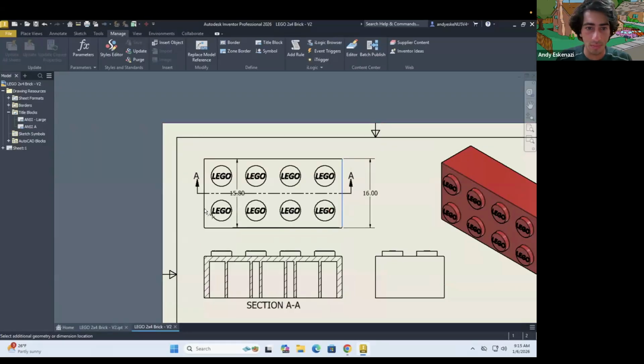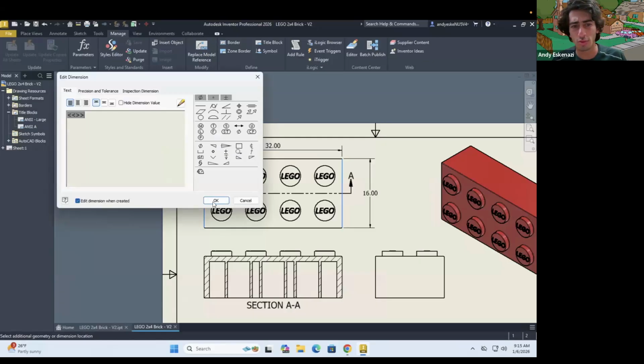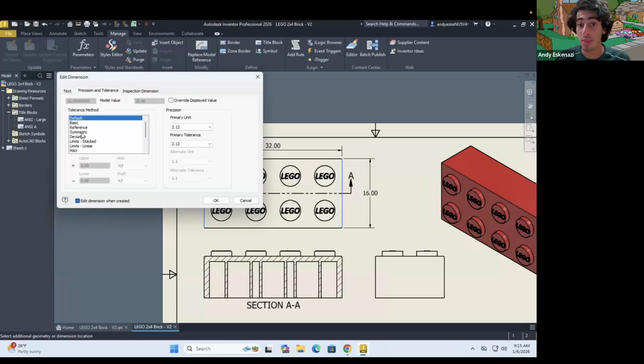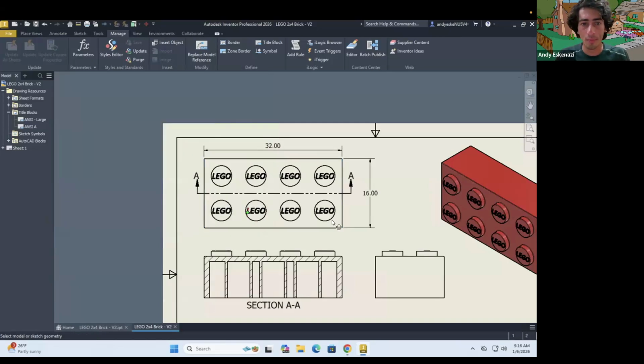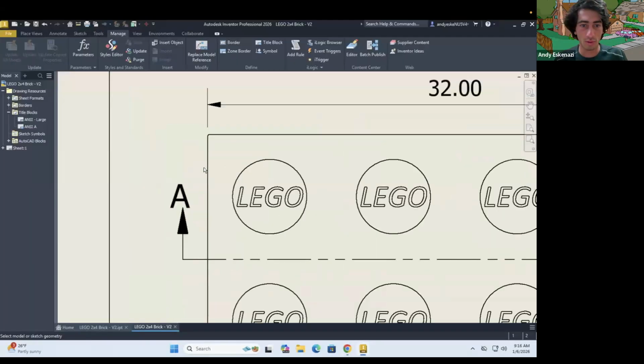So then I go here to D, and we can continue adding more dimensions right there. In fact, you can also specify whether you want these to be 2 decimal places, or since we're here, I can also specify the tolerance. Because if this is manufactured and it's using some manufacturing tolerance from whatever tool that you have, you can say, right, maybe go up to 2 decimal places plus minus a certain amount that you are allowing. So we have that. And then what I'm going to draw is a couple of lines to dimension a couple of things. So I'll say, all right, D in here, and I'll specify that that's 4. I'll say, okay. Now let me see whether yes, I can move exactly.